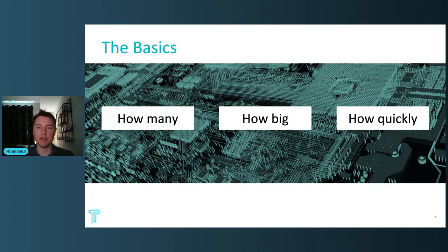So it's important to do a little geometry in your brain, figure out how many of your boards you think will fit in one fab panel. And if you don't know the answer to that question, I highly recommend just asking your CM. It can be a huge cost saver, particularly on the unit cost side, to optimize for fab panel space.